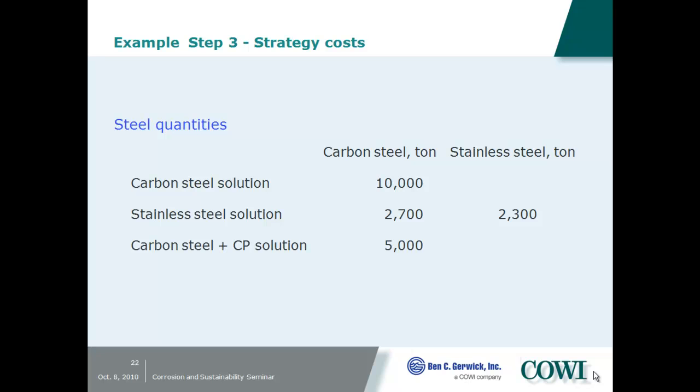But then don't you create more of a corrosion problem when you have different materials? No, not if you combine carbon steel and stainless steel, you are fine as long as the carbon steel is still in the passive area. So you need to have the zoning up. Stainless steel is a very poor cathode, so that's another issue that makes it not that bad. But you need to know what you're designing. You need to know that the carbon steel is placed outside of the risk area.